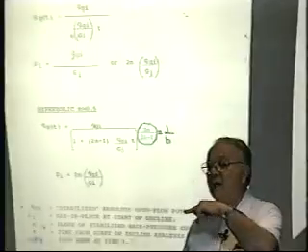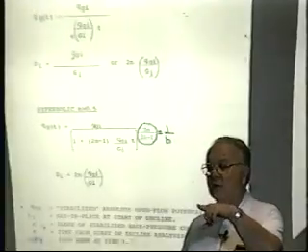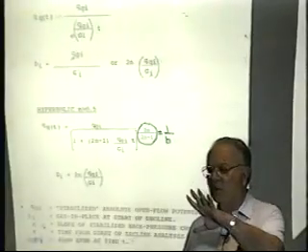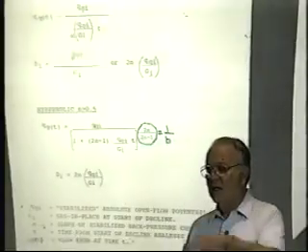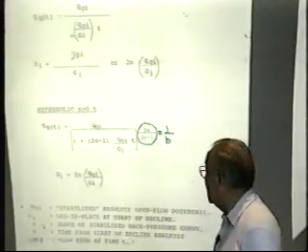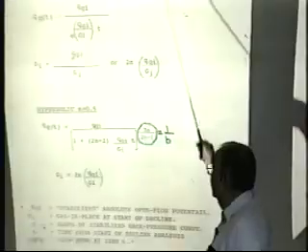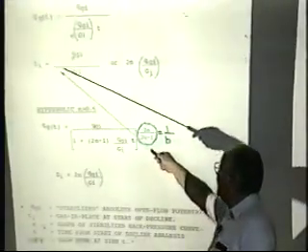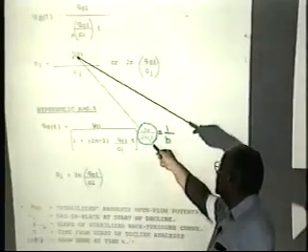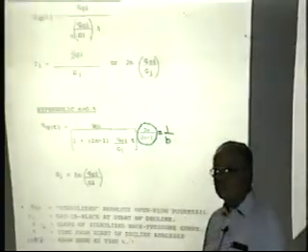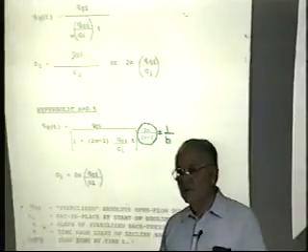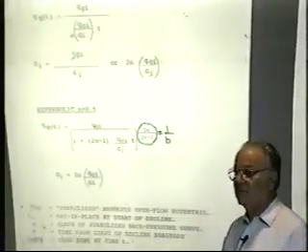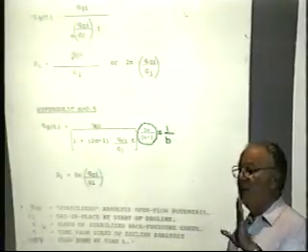We'll work out an example later where we'll show you how to treat it if the flowing pressure isn't zero. But don't worry about it. Again, this is how you end up with the equations. Very simple equations when you're going to assume the flowing pressure is essentially zero. And for exponential, D sub i is equal to the absolute open flow over the gas in place. That's the initial decline. It's got a physical meaning, and you can calculate that.